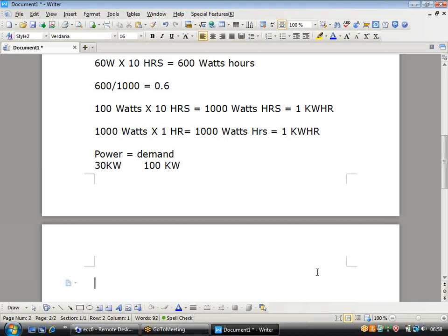But if your rated capacity, the instantaneous capacity you require for a period of 15 minutes, is 100 kilowatt, or more than 30 kilowatt, it is going to be charged at 6 rupees. That means we are altering the price for the consumption based on the power rating. So there has to be some kind of meter in the metering system, which will not only measure the consumption energy in terms of kilowatt hour, but also measure the instantaneous power demanded by the equipment and sustained for a period of 15 minutes.